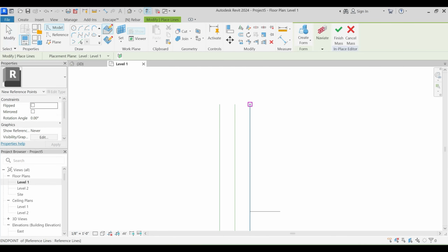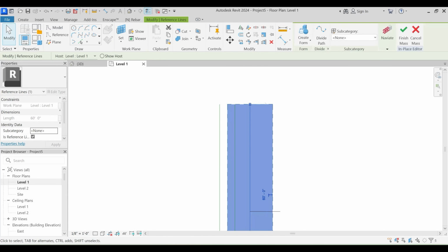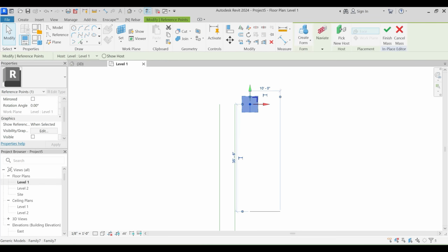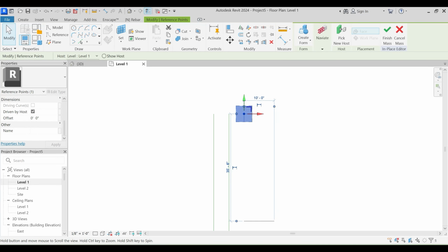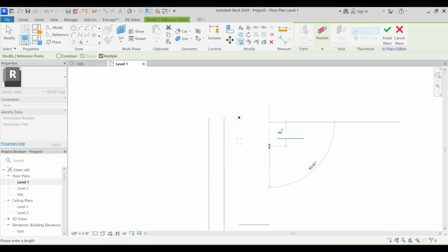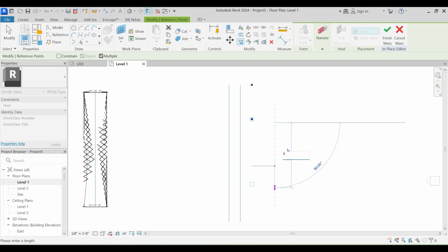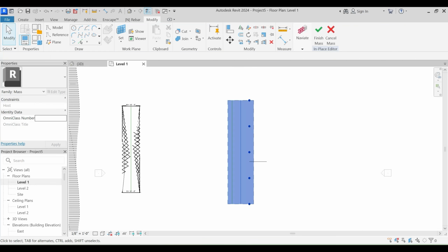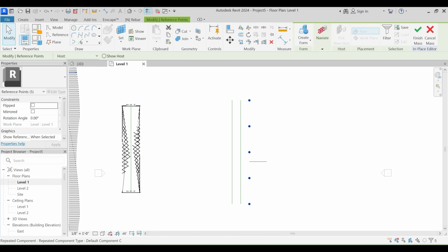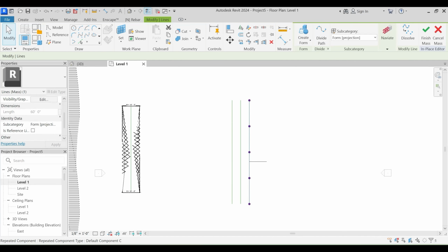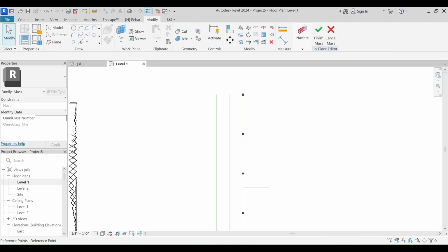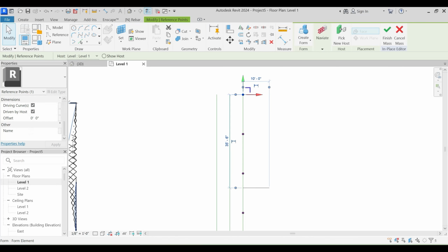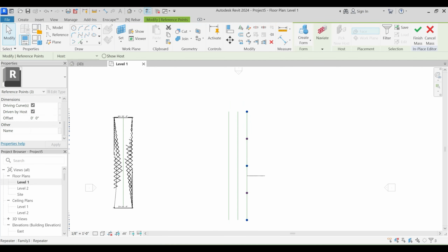Okay. So what I was supposed to do first is that I will just say that I need a point 1, and I'll select this particular reference line and delete it. And just select this particular point and see that it has this offset parameter. Fine. I will just copy this 1, 2, 3, and 4 times. Okay. And then I will select all of that and just say spline through points, and that is a reference line. Okay. Now I'll select these particular points, and you see that it has this offset parameter. So this 1, 2, and 3. There are 3 points I will select.